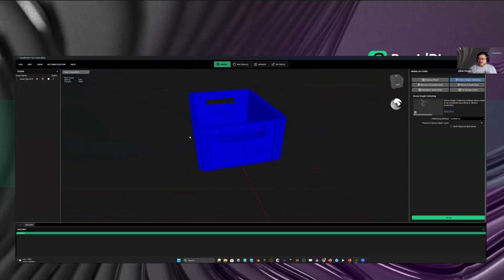So this is a cool check to see. It's not that important for render visualization, path tracing, etc. But once your pipeline ever goes real time, or you have a rasterizer where you have backface culling enabled, for example in a WebGL based viewer, having winding order issues is of course really detrimental, because then your model is half open, you have split faces in a visual way. So to make sure you don't have these issues, this might also be relevant for game engines. If you're going to Unreal later, it would be the best case scenario to completely avoid winding order problems entirely.